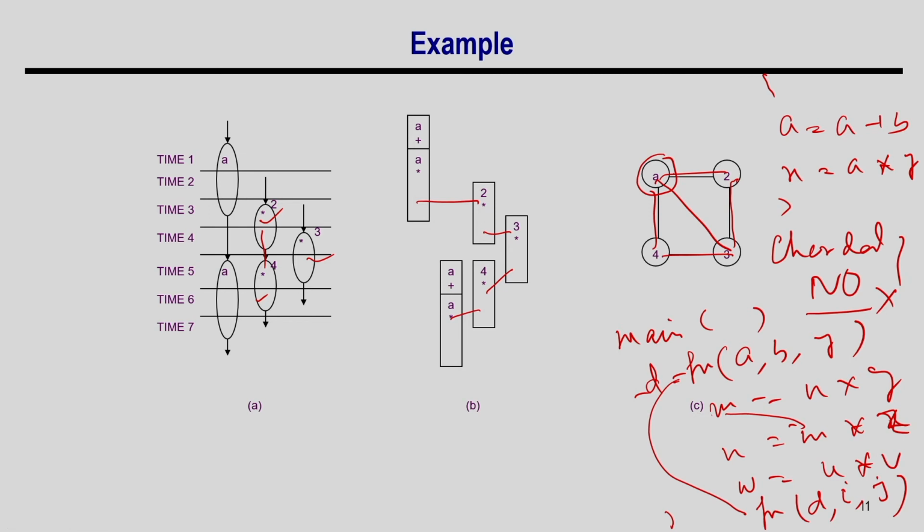So, the summary of the discussion is that even if 2 function calls overlap, I can share some of the resources. If there are 2 copies which are completely non-overlapping and there is nothing else, I can definitely have a single copy. And if there are 2 functions which have some overlapping, I still have some sharing possible for certain kinds of operations that I have already discussed.